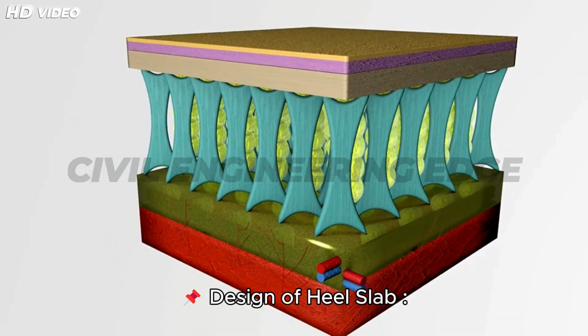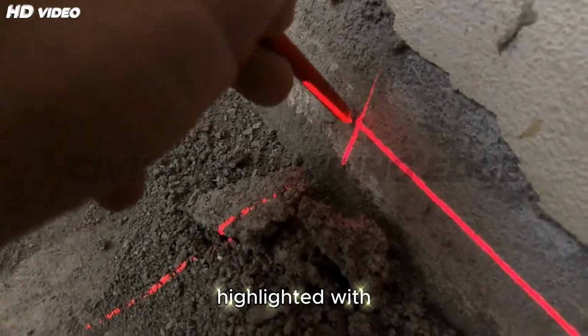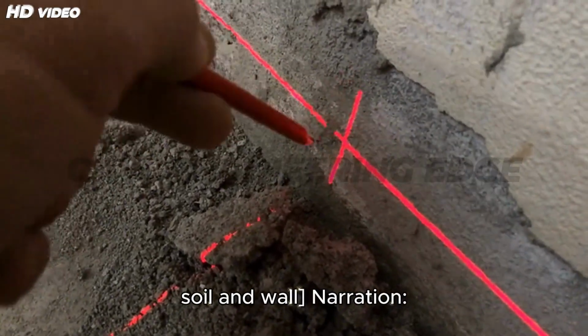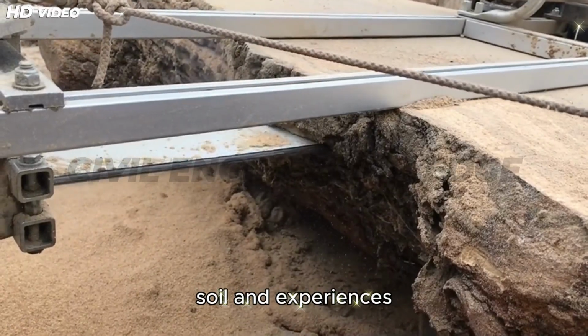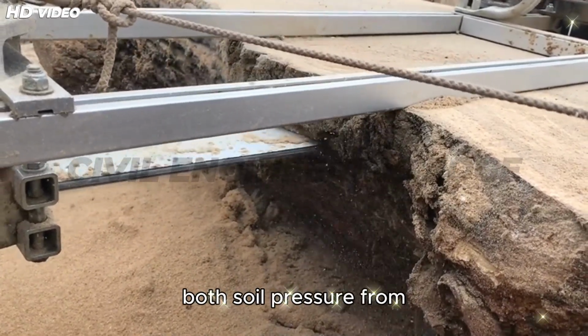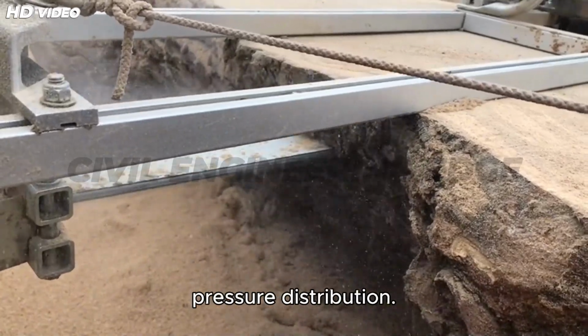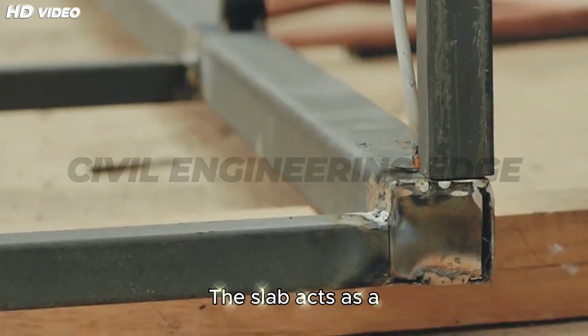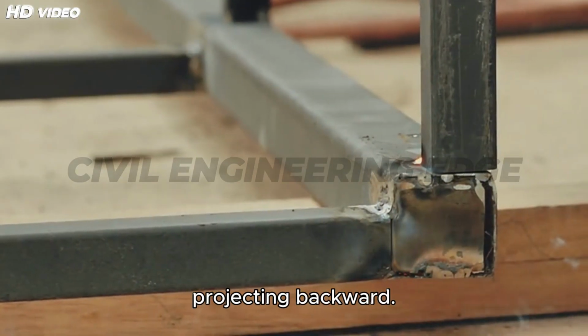Design of heel slab. Scene: bottom slab highlighted with load arrows from soil and wall. Narration: the heel slab lies beneath the backfill soil and experiences both soil pressure from above and uplift from below due to bearing pressure distribution. The slab acts as a cantilever slab fixed at the wall base, projecting backward.